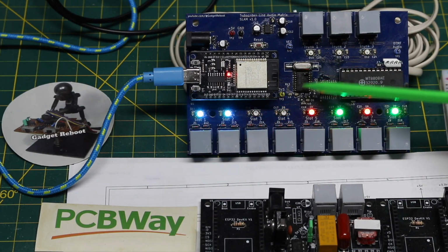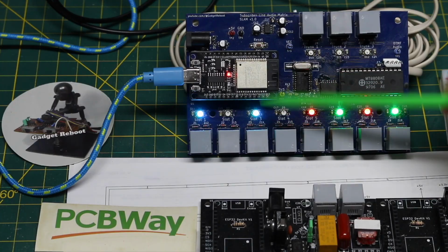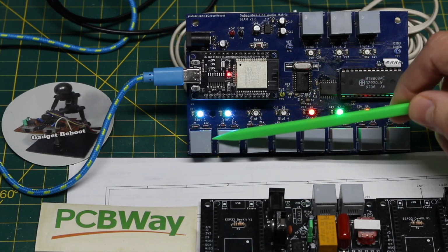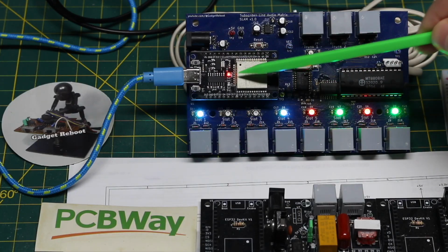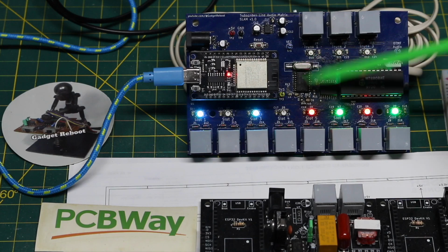There's also a DTMF decoder circuit here because possible future expansion could be that if we want to do some configurations, we could have a board sending out DTMF touch tones, and then the ESP module can detect the tones and follow instructions or change configurations.